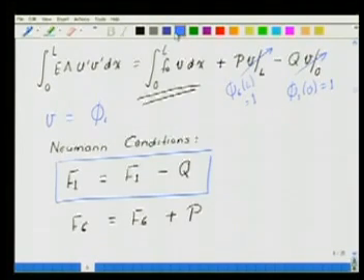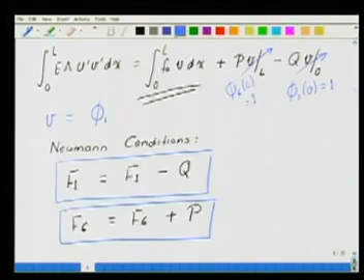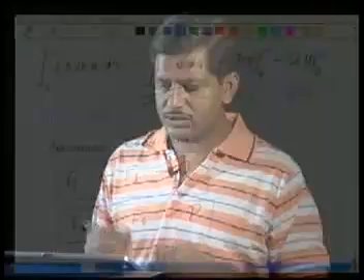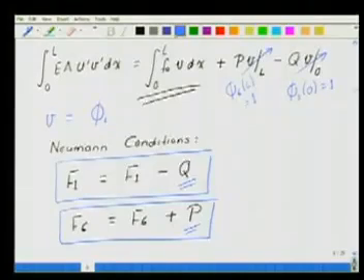So, application of the Neumann boundary conditions for this one dimensional problem is very easy. That is, you go to the corresponding rows and just add a number, because Q is a number, P is a number. Now, once we have this, what do we know about V for this problem? In this problem, V is unconstrained.